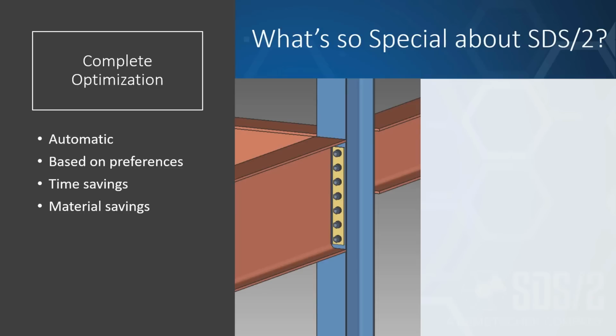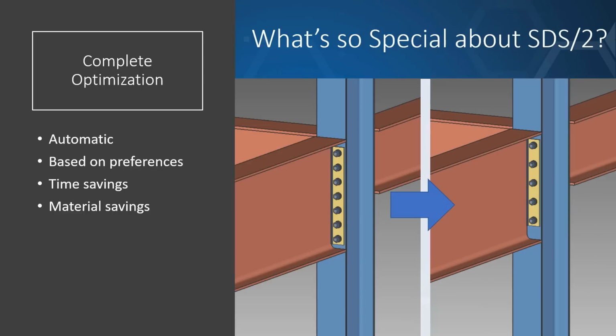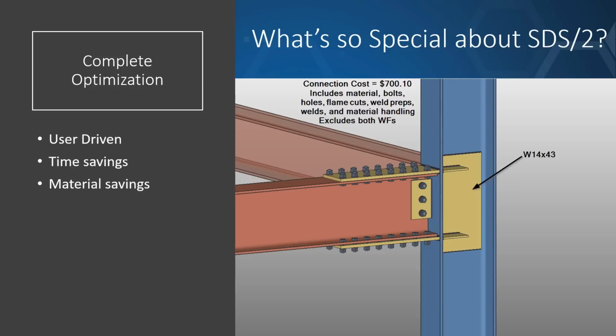When it comes to optimization, so this would be for somebody that actually cares about how many bolts there are or how much money they're spending on the bolts. So what the practice used to be is just fill that beam up with bolts. Instead, there's a couple settings that you can tweak on here. And instead of using 7 rows of bolts, it went to 5 rows of bolts, but it still passed that connection. So that's just another automatic optimization that you can do.